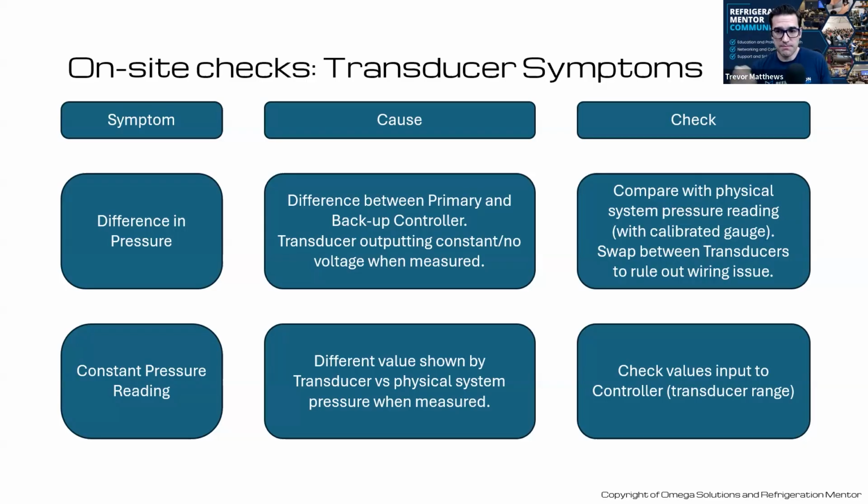And so what he did, he took his high pressure gauge, put it on the flash tank, and it said 580 PSI, so around 40-ish bar. And he's like, what's going on? So he actually pulled off the transducer and it was full of oil. He just emptied it out of oil, put it back on, and it read correctly. So some things can be a little tricky like that. And I've talked to a few manufacturers that do a lot of support, and they've seen a lot of technicians cut valves out or replace valves for actually a transducer issue or a wiring issue to a transducer.